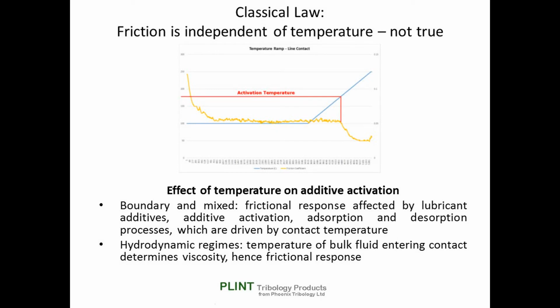In a lubricated contact, friction is not independent of contact temperature. In the boundary and mixed regimes, where frictional response is affected by lubricant additives, additive activation, adsorption and desorption processes are driven by contact temperature.